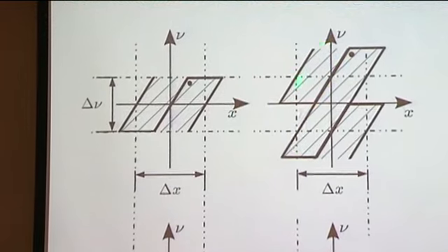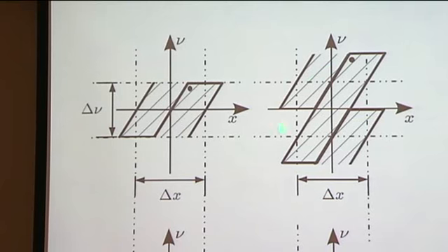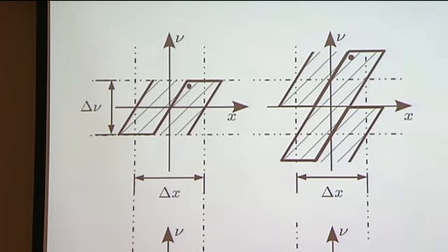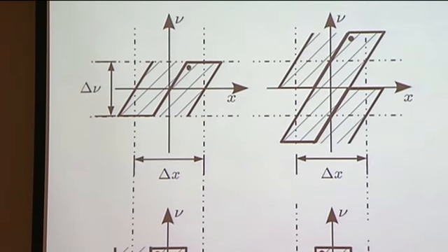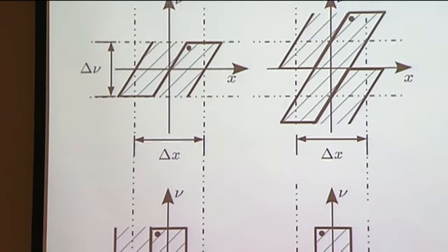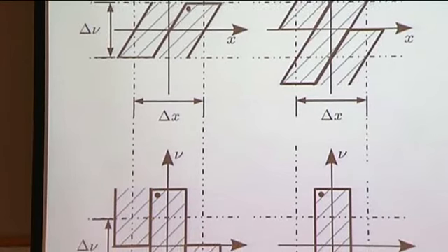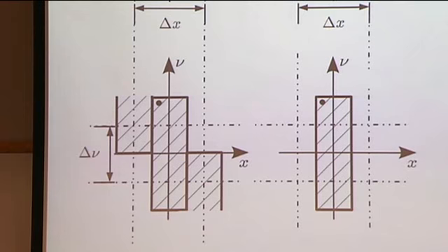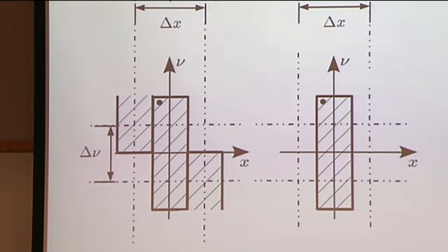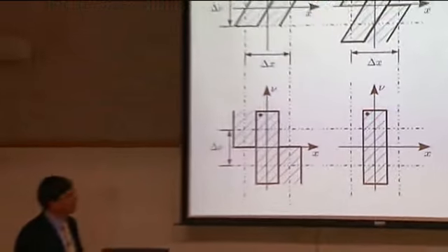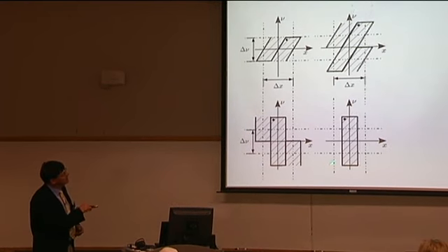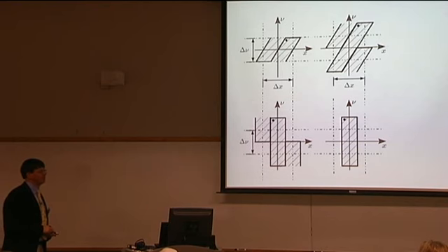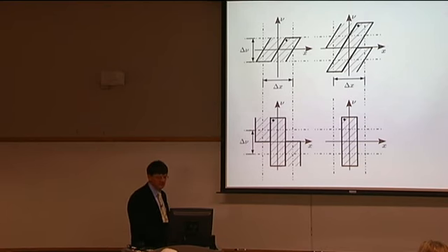And again, we need to make two copies, one shifted to the top, one shifted to the bottom. And as a result, we get our original signal back. We can back propagate this to an image plane, cut away what we do not really want, and have transmitted a signal with double the bandwidth, but we had to restrict the size of the object. We have had to cut the object size in half.